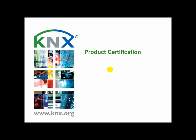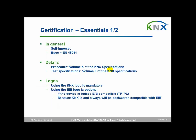So topic 1, product certification. So the essentials are as follows. So first of all, KNX product certification is self-imposed, and the base for KNX product certification is the standard EN 45011. In detail, this means that the procedure for KNX product certification is to be found in volume 5 of the KNX specifications. The actual test specifications, they are to be found in volume 8 of the KNX specifications.